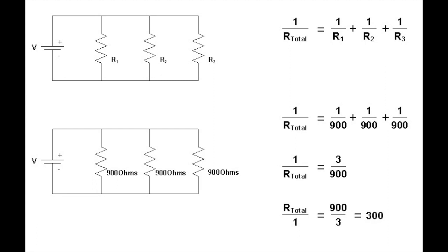In a parallel circuit, it gets a little bit more complicated. For some of you, you get this, and yep, you've got it dialed in, it's a walk in the park, just a refresher. But for some of you, resistance in parallel is one of those that you might not be able to get your head around. It's an inverse formula, and that formula looks like 1 over RT equals 1 over R1 plus 1 over R2. It means that the more resistive values you have in parallel, the less the total resistance. They are inversely proportional to one another.